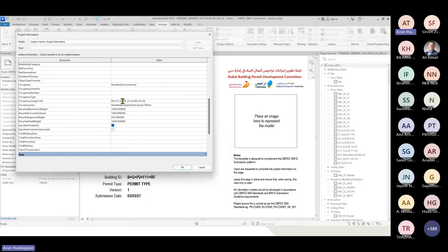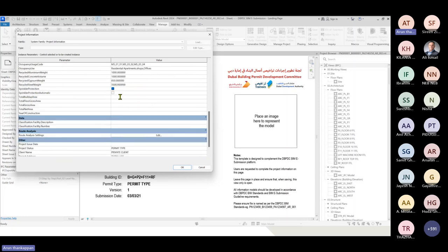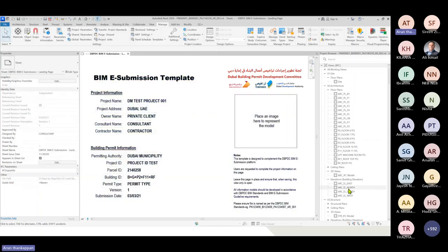After a comma separation, you have to add those three codes, and the description the same as in the Excel sheet: residential, shop, and office, and the master of the project, residential and commercial. Once you calculate all your gross area and built-up area, you can add the values here. So that's all for IFC project and IFC building.